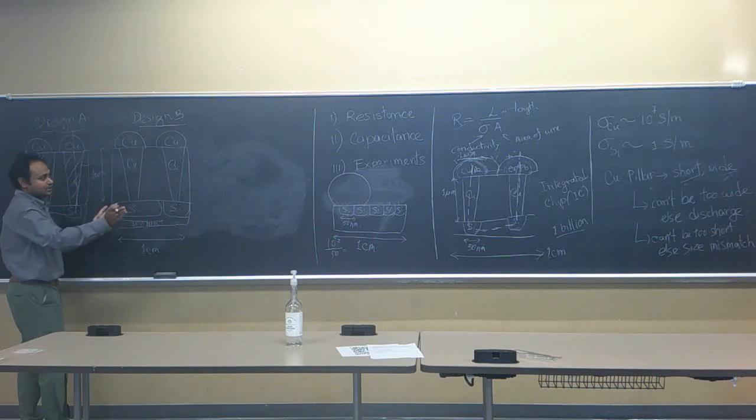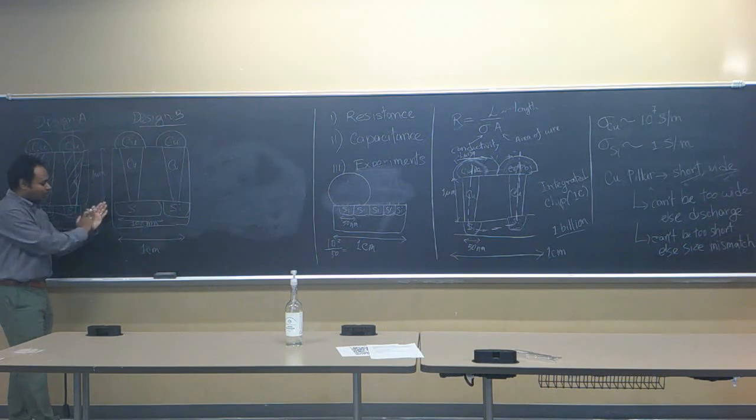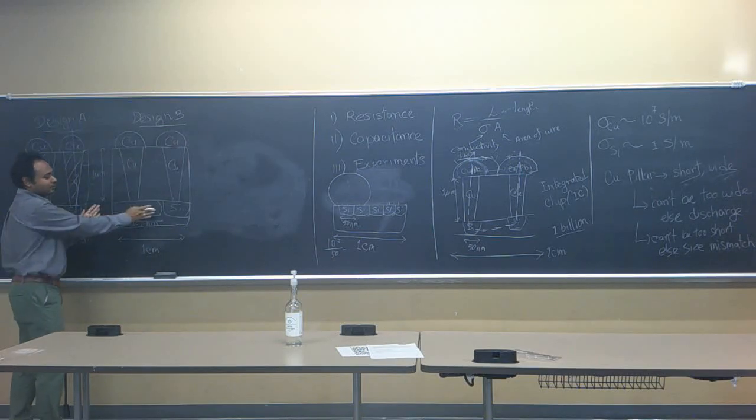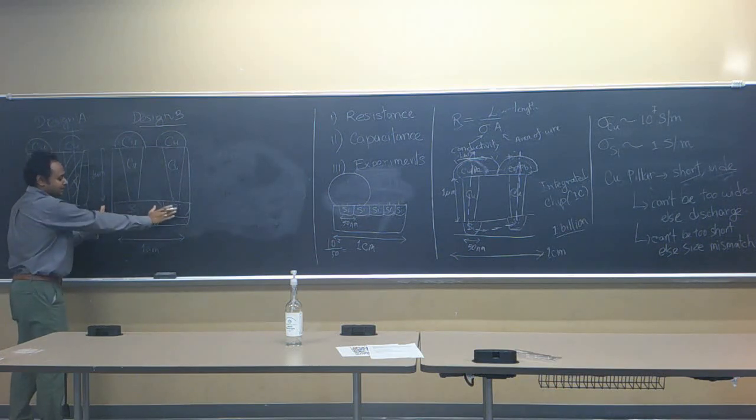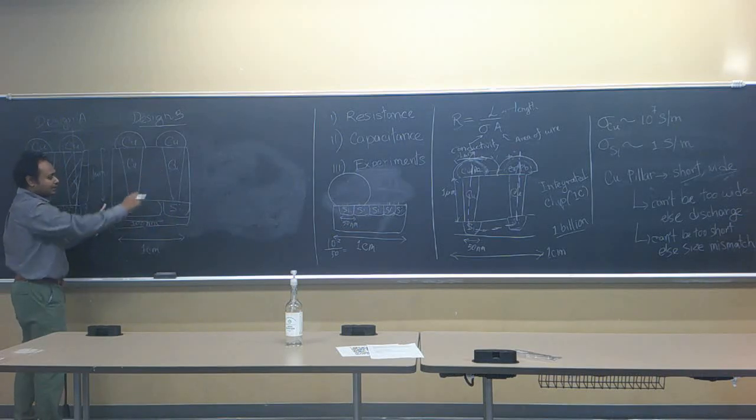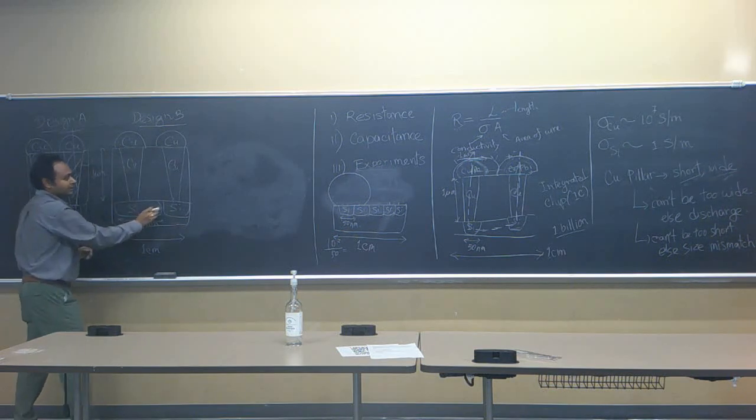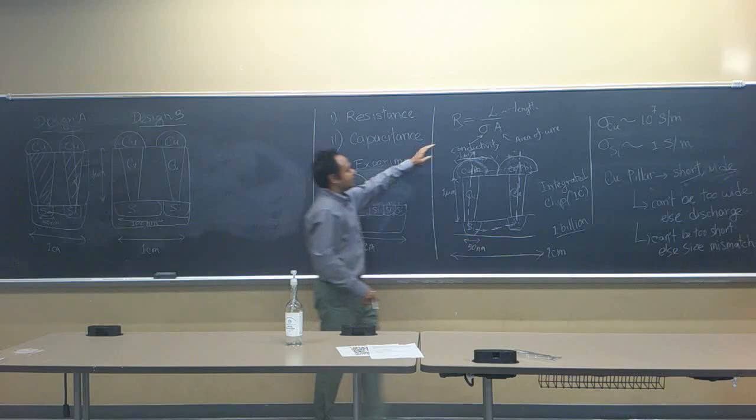So in a similar way, in order to reduce the resistance, we have two options for a silicon device. One, we can make it very big, very wide into the plane of the board, but that makes the number of silicon devices very small. We want to make as many silicon devices as possible inside this IC. So the other option is that you make the silicon device very short. If you make them very short, then the length would go short and the resistance would become minimum.